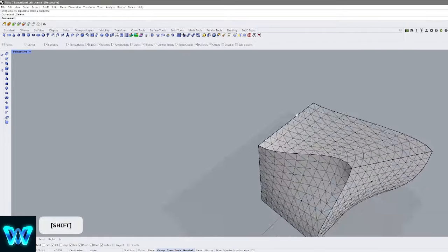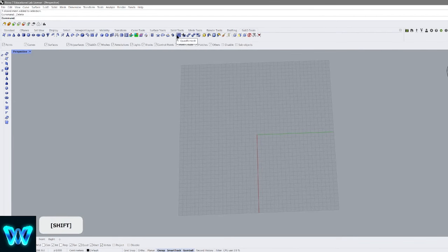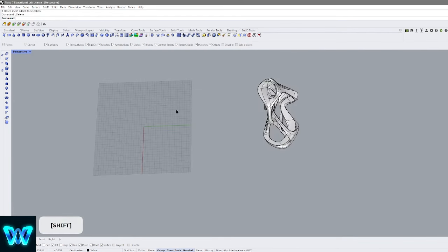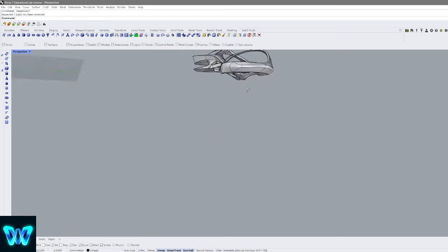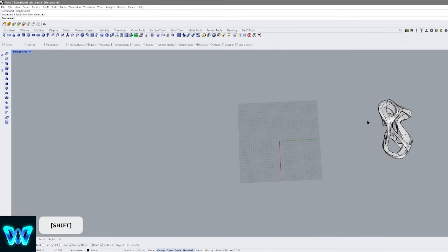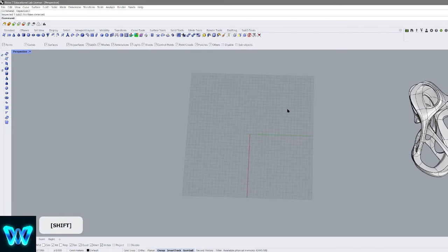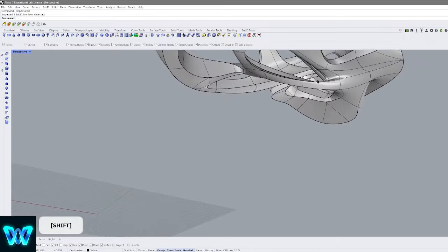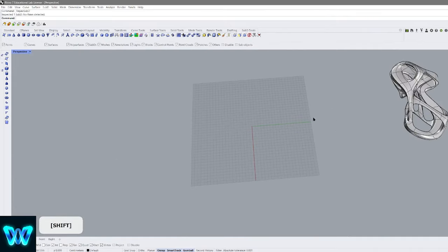It's a really useful command, but be careful when you have really big meshes and you're trying to create a lot of faces, because it can crash your computer pretty easily. This one right here is just repair SubD. Whenever there are flaws in your SubD, this one has no flaws. But whenever you work a lot on a project and you have a lot of different phases, things can get a little complicated. So you might want to press repair, and it might fix a couple of things that you're not aware of, such as missing faces, flipped faces, curves that are intersecting, etc.